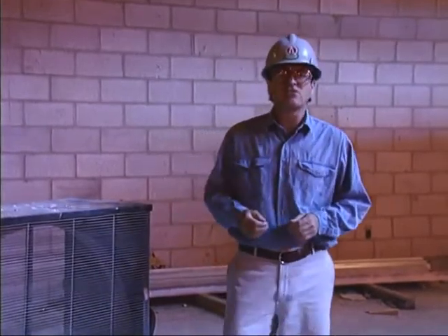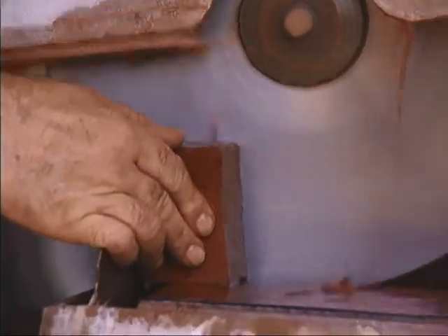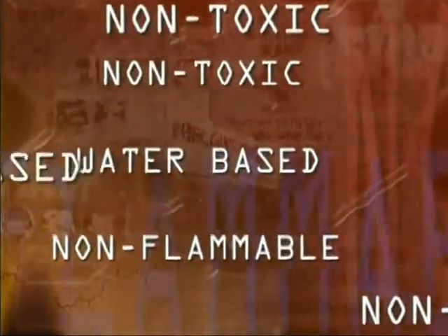Some examples of engineering controls include using fans or blowers to provide fresh air ventilation, using wet methods during grinding or sanding to help keep dust out of the air and out of your lungs, and substituting other, less hazardous materials for the chemicals being used.